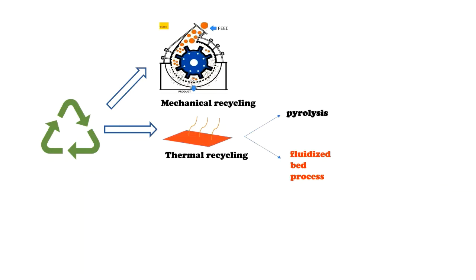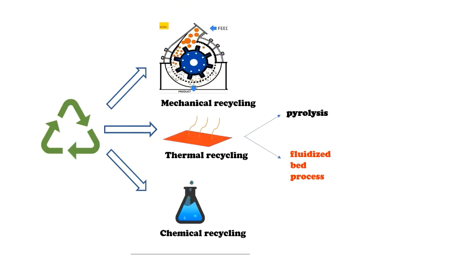The third method is chemical recycling. Chemical recycling process uses a solvent such as water, acid, and alcohol to degrade the resin and recover the carbon fiber. The process is able to recover high-quality carbon fiber with loss of tensile strength and recover the polymeric matrix. Recovered carbon fiber provides opportunities to reduce negative environmental and financial impacts compared with virgin carbon fiber production.